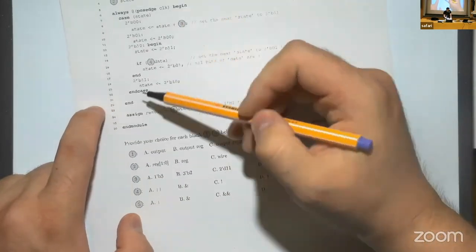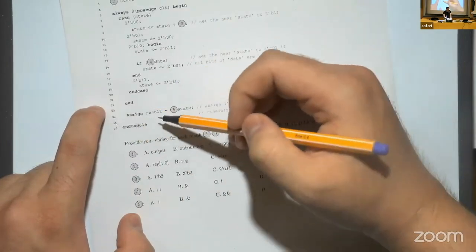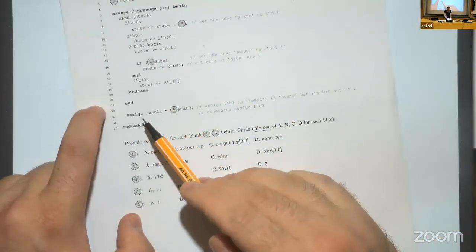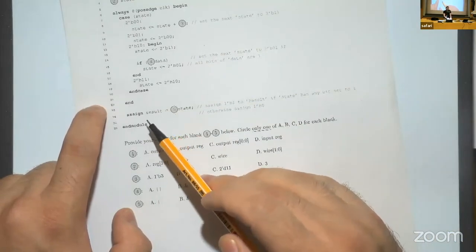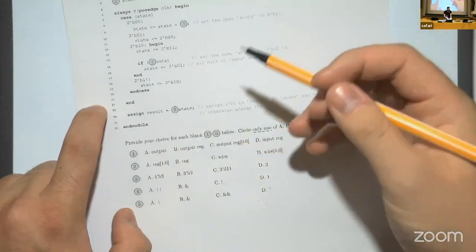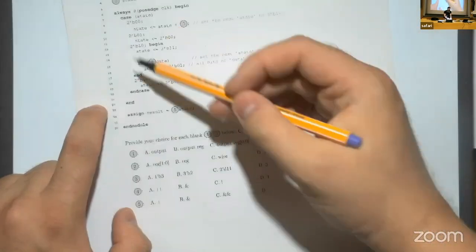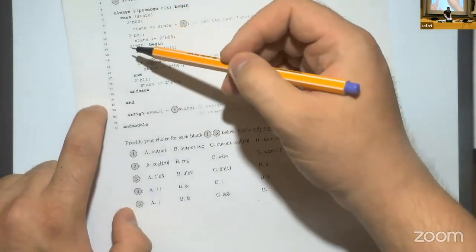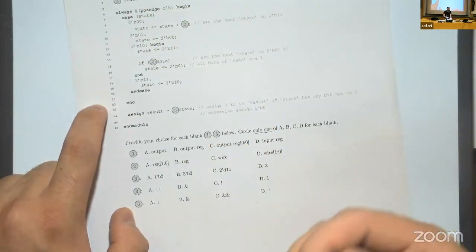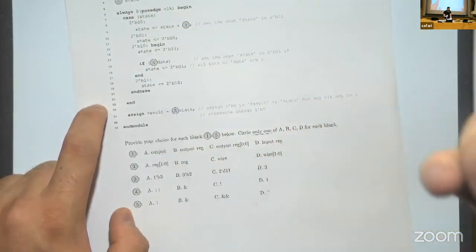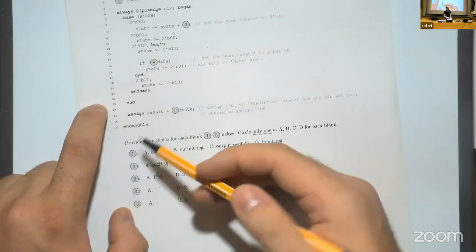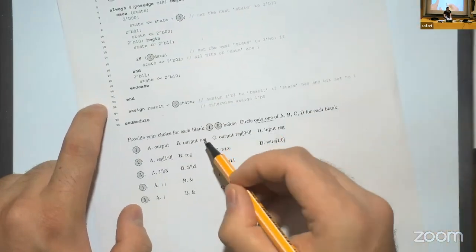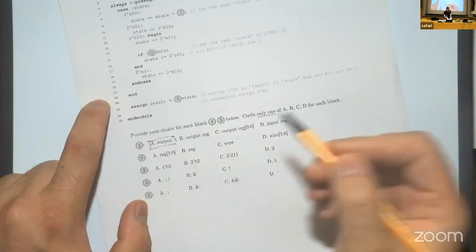So when we check line 24, we see that they used assign. So if it was reg, we couldn't use assign here, because reg can be only updated inside the always block, and we cannot use the assign keyword for this one. We should use it like this with state. So which means that result is wire, and we won't use reg over here and here. So which makes A the correct option.